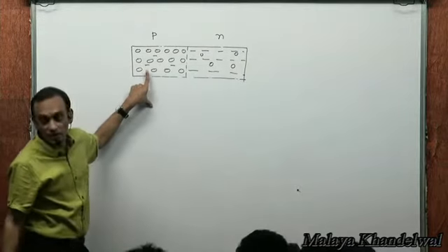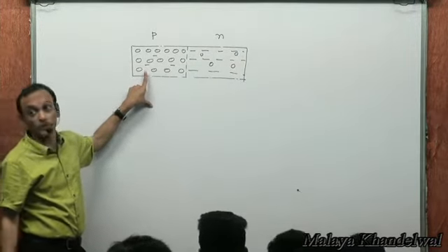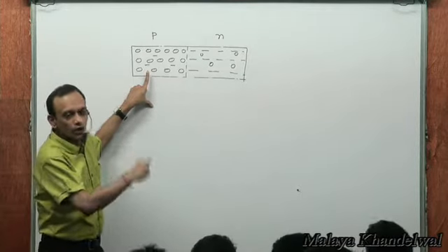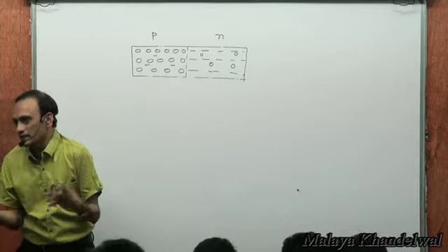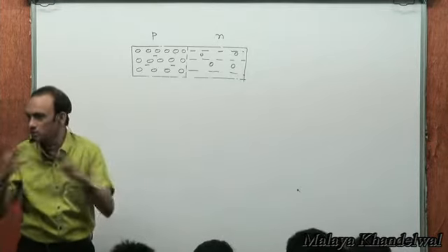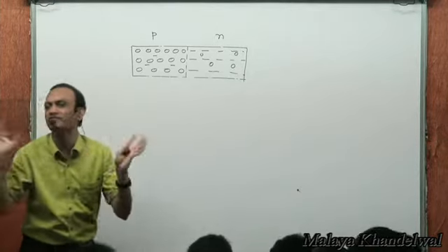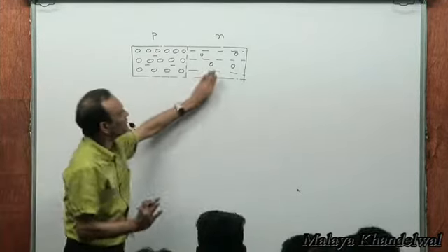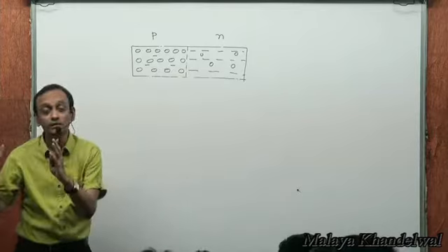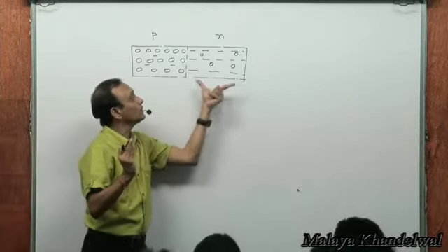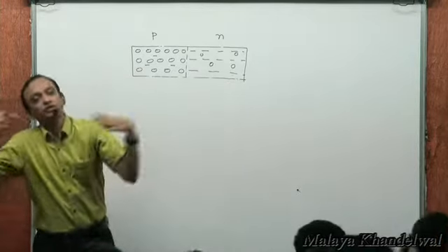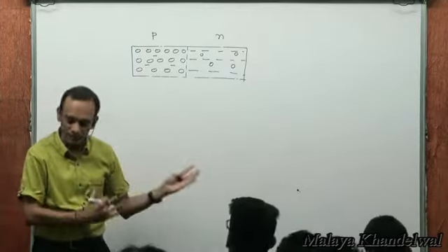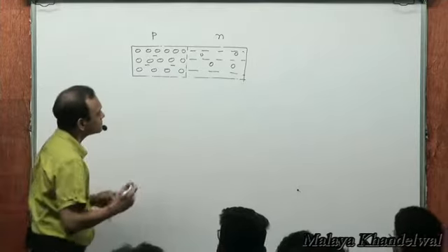Does it mean that the p-type is positively charged? No, it's neutral. When you're doping it with a neutral atom, isn't it? And the original material, the silicon crystal, was also neutral. So you've not affected the neutrality. You have just created a redistribution. Same with the n-type. In principle, the whole piece, the whole length would be electrically neutral, right? We are talking of charge carriers as being in majority and in minority.